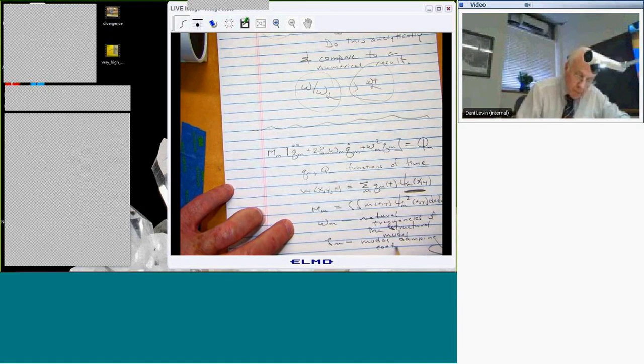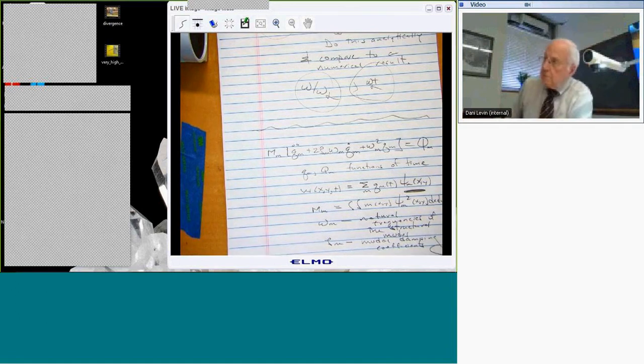Which come from where? Experience. Possibly an experiment. Although even with an experiment, if you have 17 modes, you're lucky to know 2 or 3 damping coefficients. And you make a wild guess, well, not wholly, an educated guess, about the other 14.